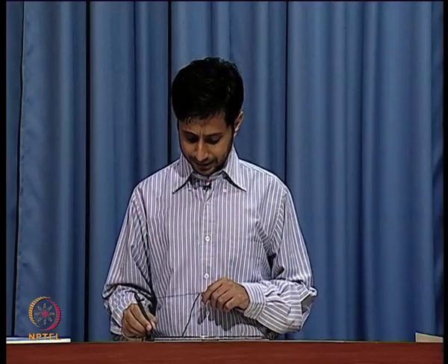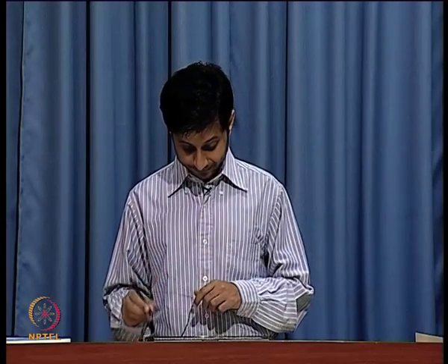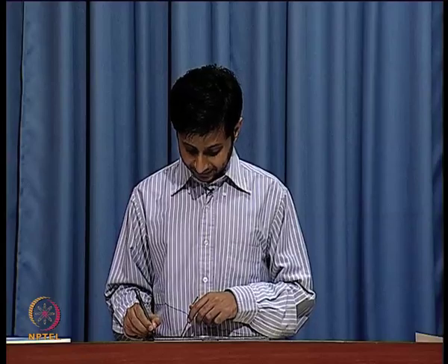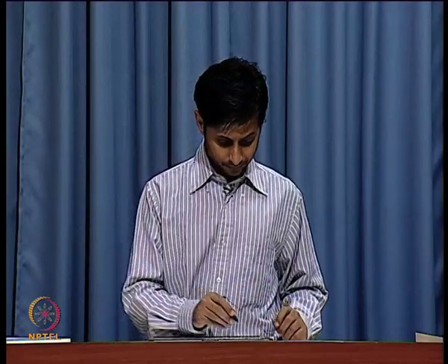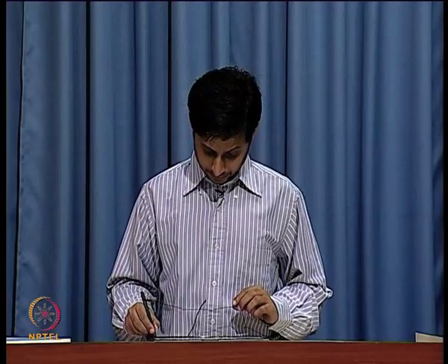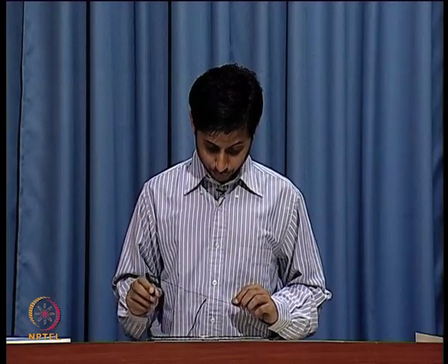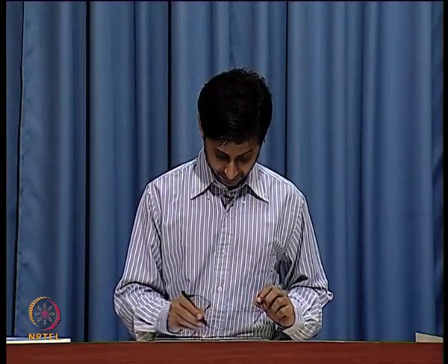As long as the channel is conducting, you really can't call this a capacitor. I do not see a capacitance here. All right. Now, let us discuss the junction capacitance, that is drain to body and source to body capacitance.